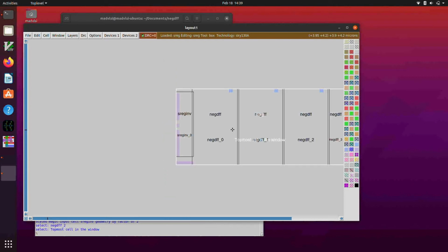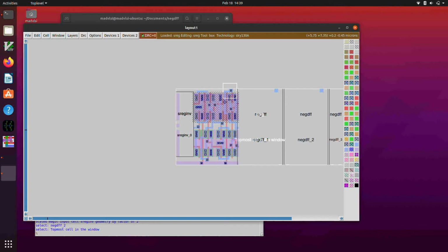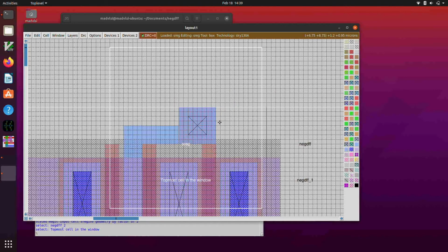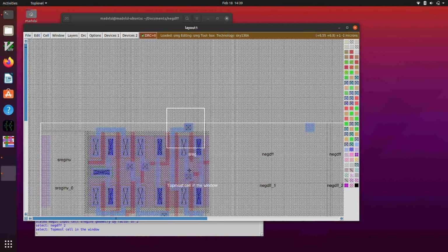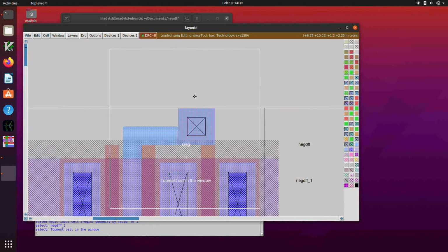And then I've taken the outputs of the shift registers. If I show this one and zoom in here, this piece of local interconnect up here happens to be the Q output of the cell. So that is a convenient place to take a parallel output from my shift register stages.